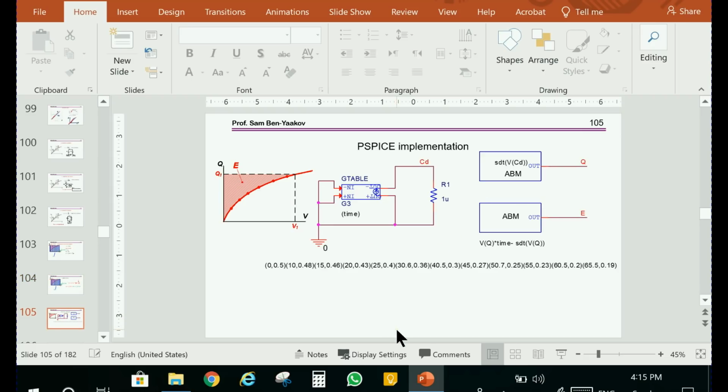Now, again, in SPICE, we can very easily get this area. I'll not go over it in details, excuse me, because I'm afraid that I may not finish all the slides. And again, I can generate back the derivative, take the integral of the derivative gives me the Q curve, and then I'm doing this area. This is this area, this first part here, and this is the rest of it, and here is the energy.